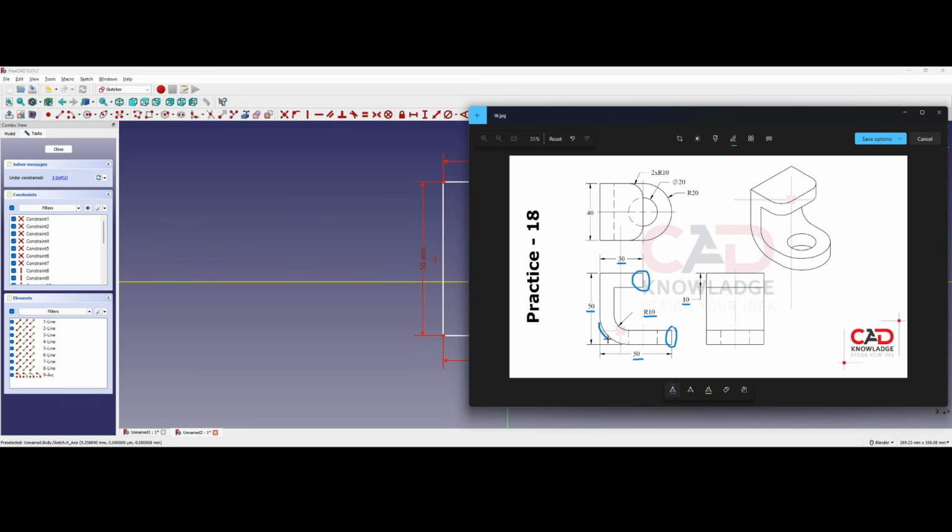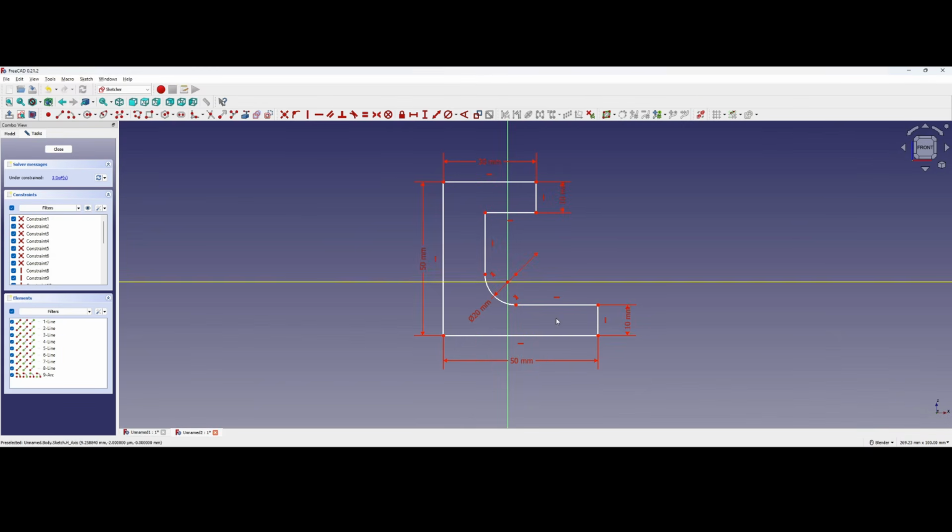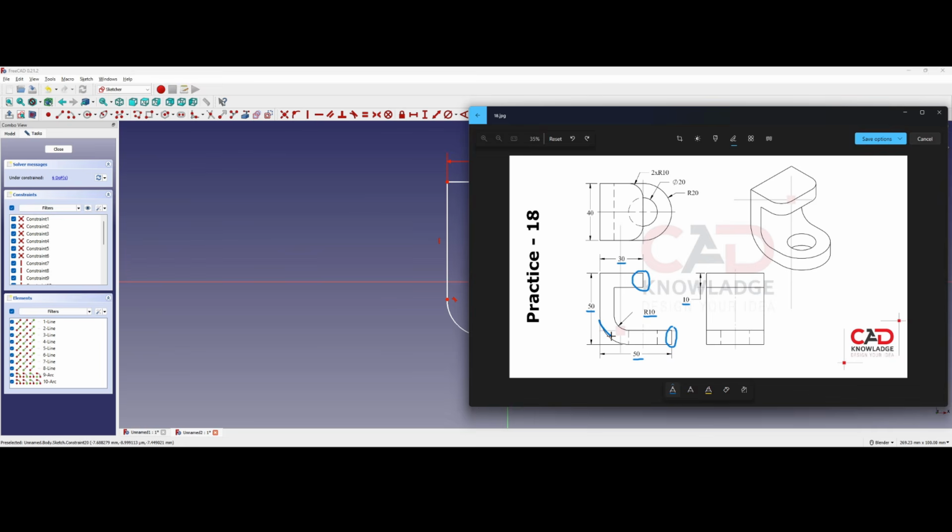Okay, and we'll need a fillet on this face as well. So using that fillet tool, I will select this leg, and it created that fillet for us automatically. You can see we've lost our vertical and horizontal constraint down here, so we'll need to correct that. But first, we'll want to get this arc in position to match up our sketch here. It doesn't actually define the radius for this arc for us, but we can see it's pretty much in line with the arc we had created initially.